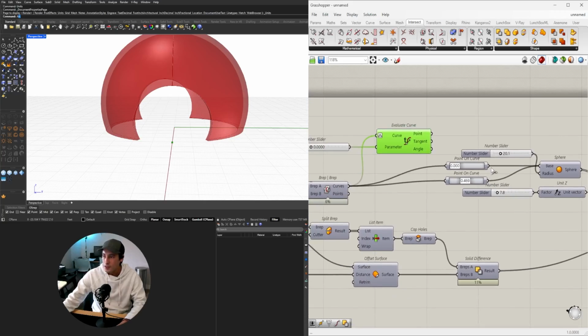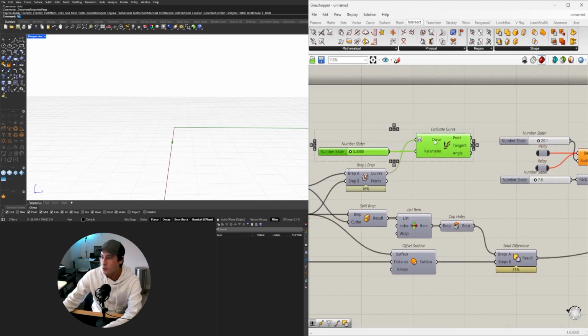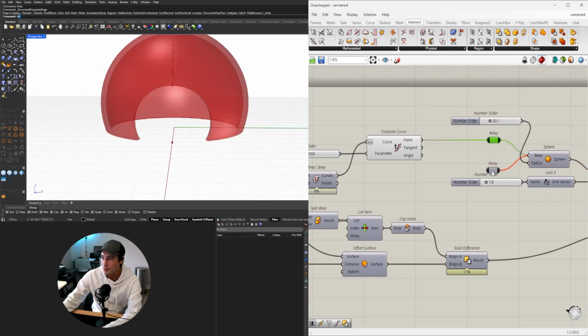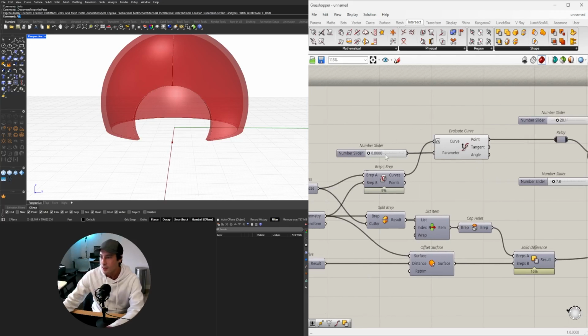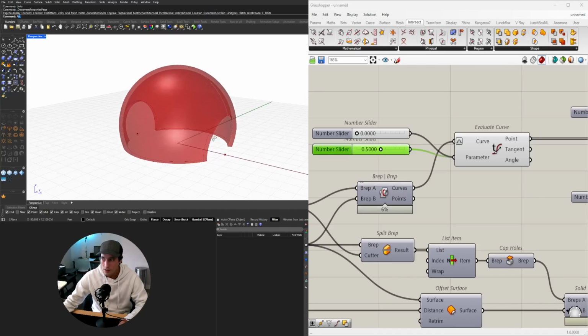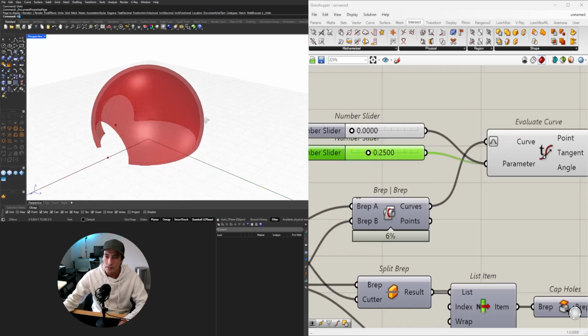So how do we do that? I'll double click here, and just delete those, because now we have a new point. It's going to be this point. And then if I want it to be at 0.5, then I'll copy this, hold down Shift and add another one, and then go here to 0.5. So if I want to add every 4, we'll do 0.25, 0.5, and 0.75.